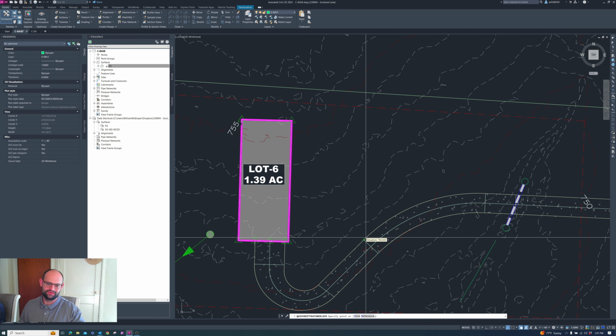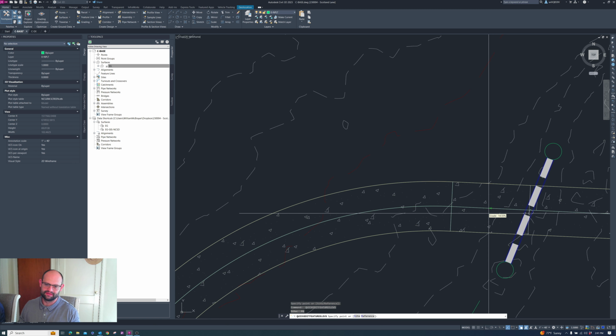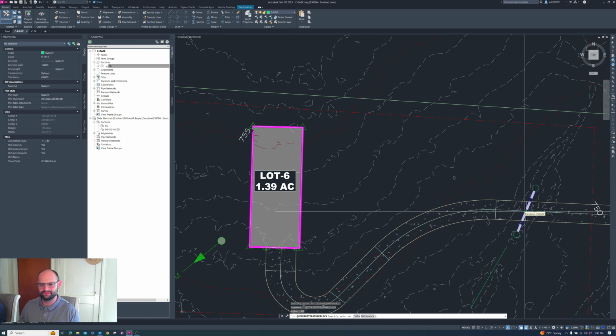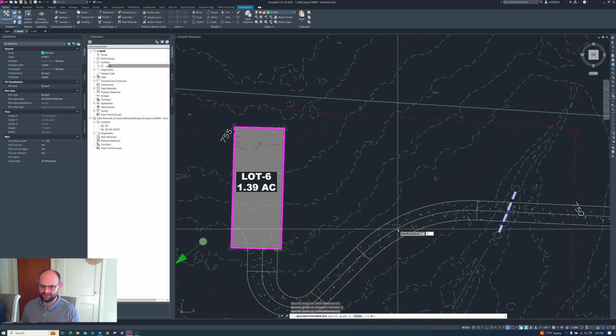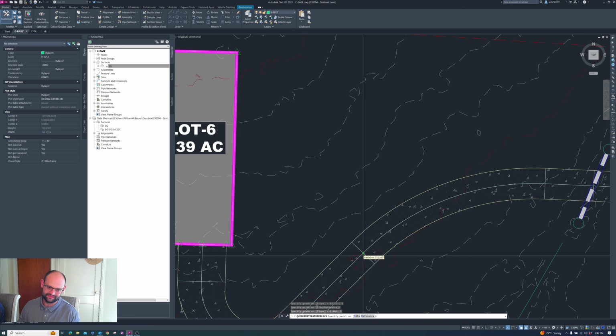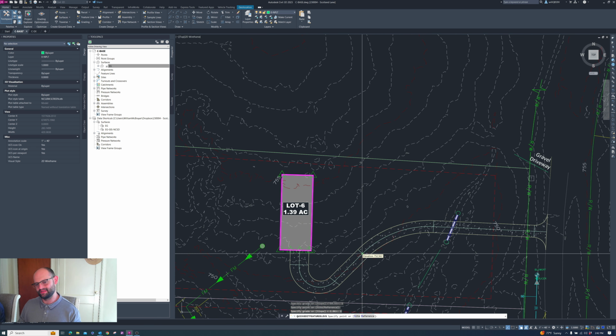Already these elevations were set to existing. Let's just go up a foot to account for the pavement section. Let's make that 751. I believe that actually made us lower than the low point here. So perhaps we shouldn't do that. Let's work away from this low point at a percent up. Percent up. See where that landed. 752.56. That'll probably work out a little better for the aesthetics of this.